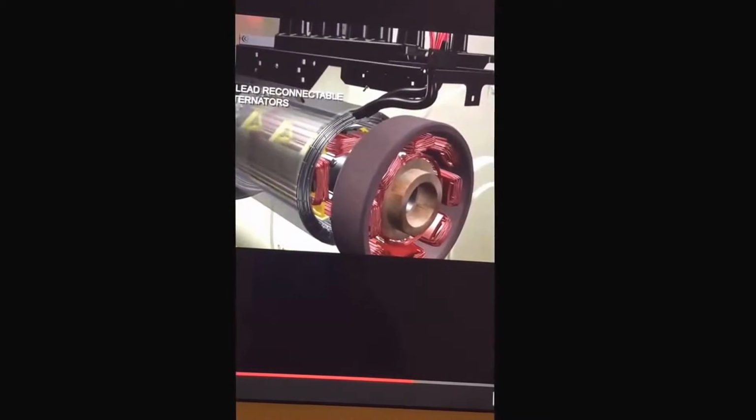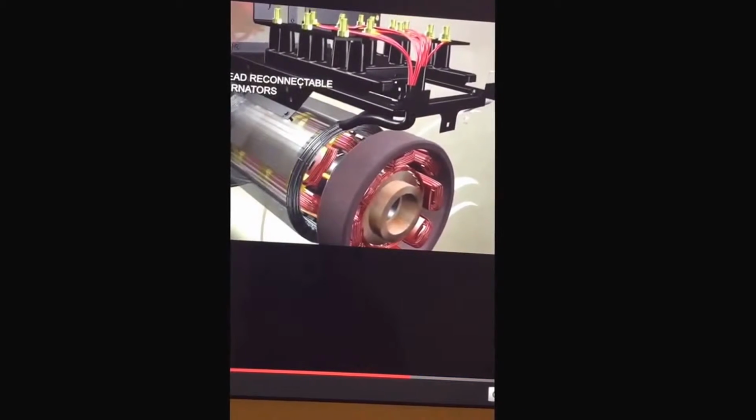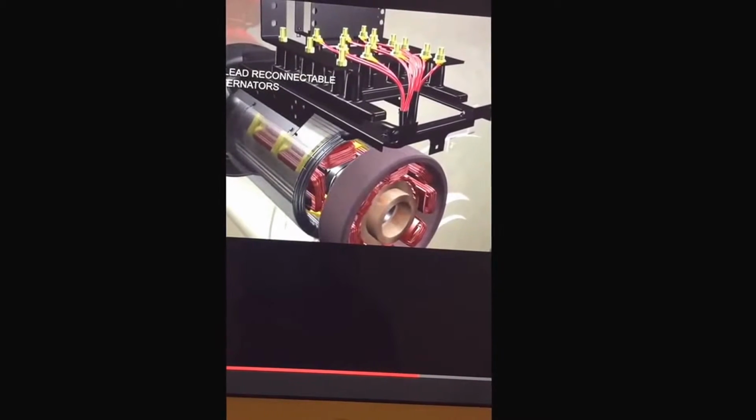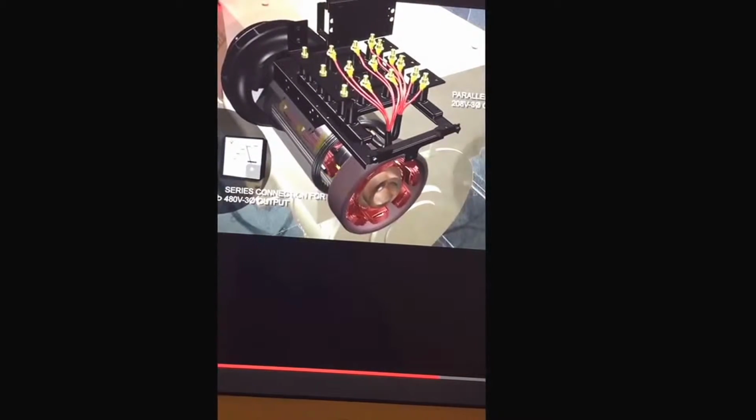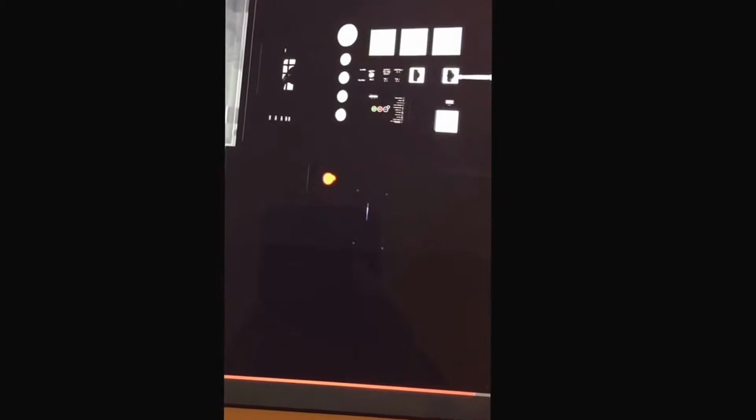Doosan mobile generators also include alternators with 6 coils wound into the stator. This provides 3 voltage sources or phases. Because each phase combines 2 coils of wire, the sources can be connected in series for high voltage applications or in parallel for low voltage needs. To simplify wire connections, Doosan mobile generators have a convenient selector switch. When an operator selects the desired voltage, the switch adjusts the connections.